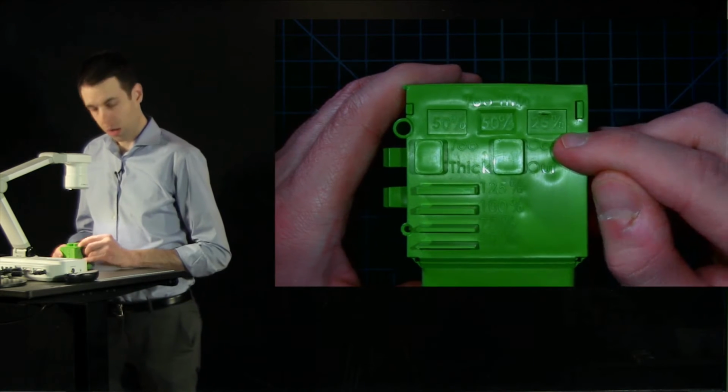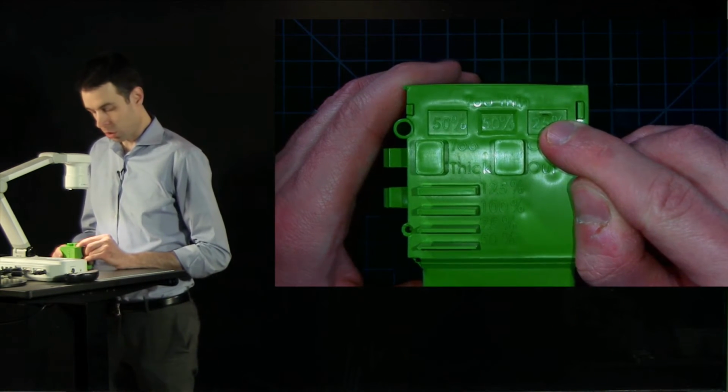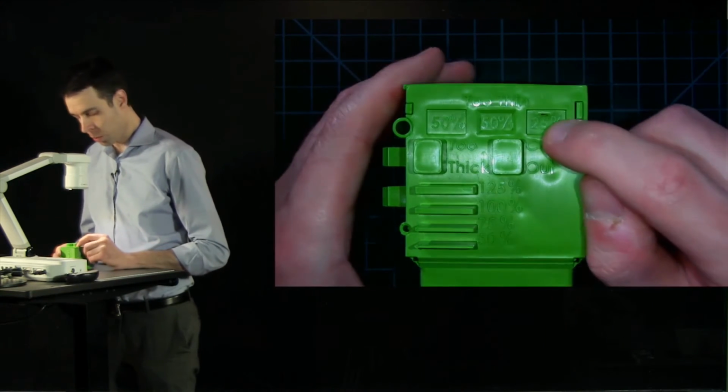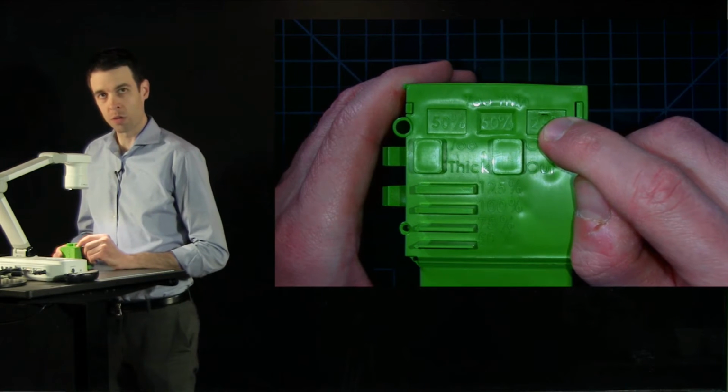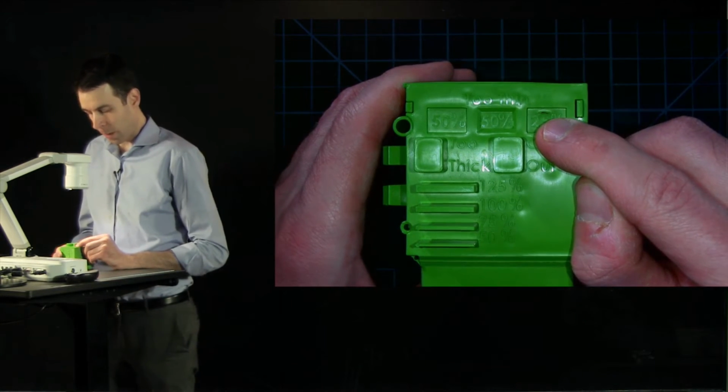And you see on the thinner one there's a void, and this void is exactly a short shot that we just learned about. It means that as the plastic flows through the unfolded cube, the pressure is not high enough, or the flowability of the plastic is not high enough to completely fill this thin area.